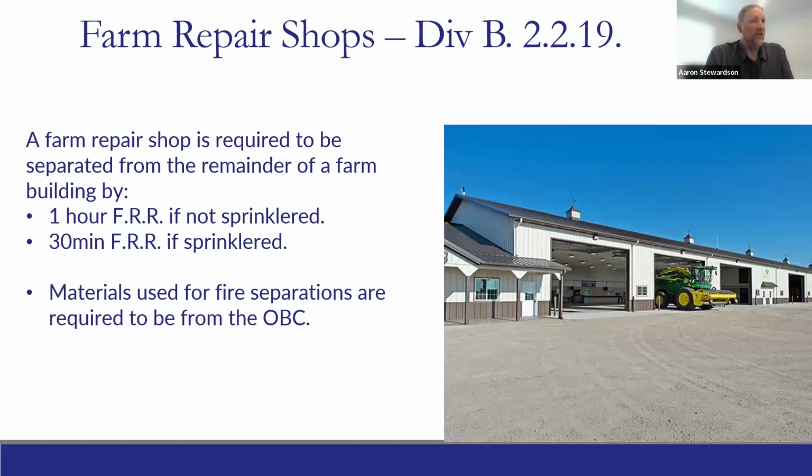One thing that has changed is farm repair shops. Specifically, there is a clause in the code now that dictates that all repair shops have to be separated from the remainder of a building by 1 hour if it's not sprinklered and 30 minutes if it is sprinklered, right?